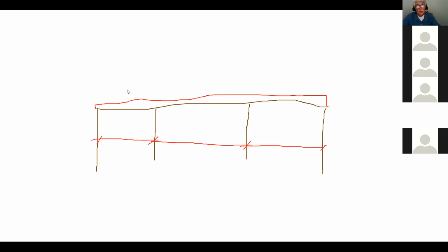basically, if you tell me it's got just one load here, you have to determine that. And then how do you determine that? Well, you find out what it is supporting, you find what the tributary width is of this beam, and then you multiply by the tributary width and you've got your load. And of course, you're going to have to factor those loads and you have to determine your WF, okay?